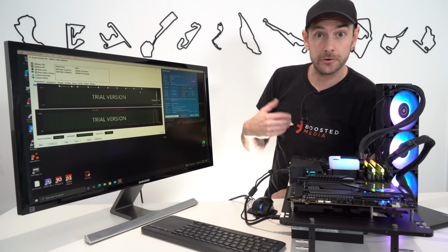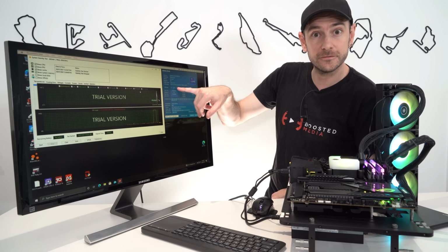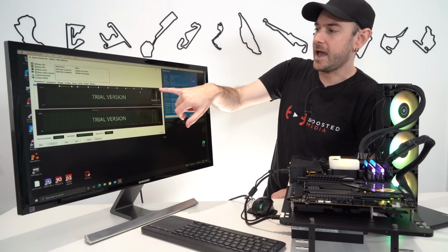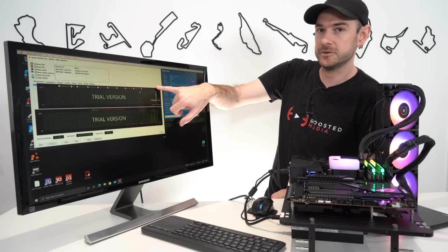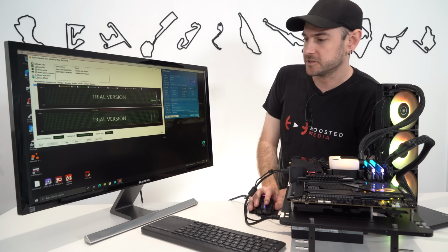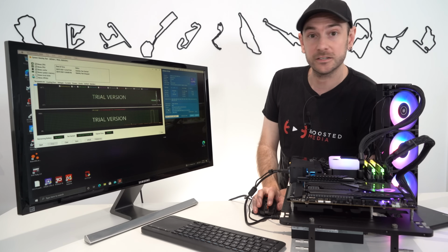And that is, in my opinion, quite an inefficient overclock, because you can see when we're running under full load across all 8 cores, we're clocking all the way down to 4.7 gigahertz, and we're also running at a very, very high core voltage, which is unnecessarily high. And as a result, we're getting high temperatures, which is going to induce thermal throttling. So what we're going to do now is close all this off. We're going to go back into the BIOS and make some adjustments.